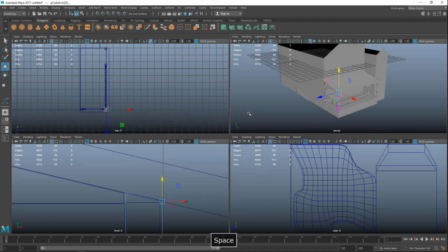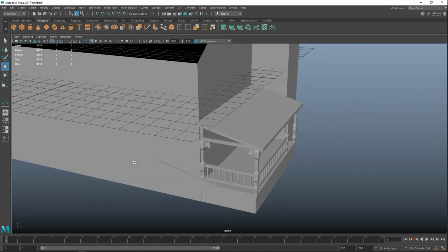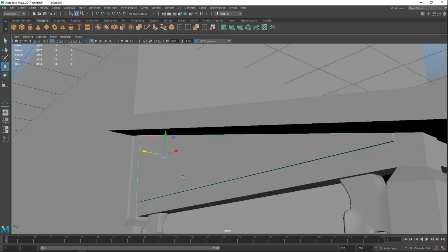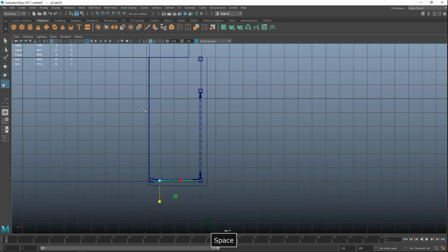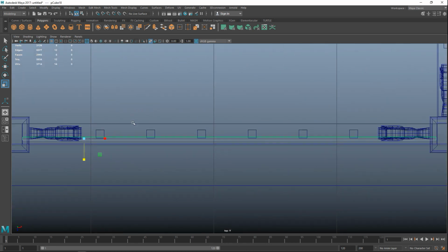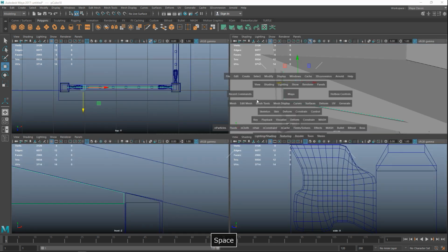Reason being that once you have lighting set up in your scene, you'll see that it will add some realism to it. And let's bring that in. Have to zoom in. Let's hit R to scale that in a bit. And we'll check it from the top to make sure that it's positioned correctly. So we'll hit W, move it in to about there, and that should be good.